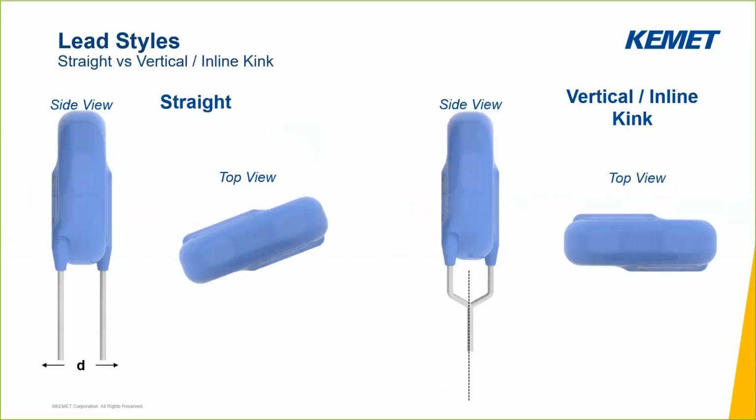Now, in this slide, a comparison can be made between the straight lead and the vertical or inline kink. Since disc capacitors have some distance between the electrodes and the lead wires are soldered to those electrodes, this offsets the leads by some distance. When mounting on a circuit board where space is a concern, this causes the disc to be rotated. In the vertical or inline kink, the leads are bent to be in line with one another and allow the disc to have no rotation on the PCB and keep the mounting holes directly under the capacitor for very high density mounting.